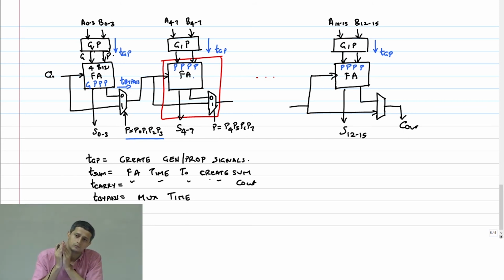Dependent on that, it means the arrival time of the output also will not count, like the input is changing, but the output is not changing for that particular case. Correct. So the arrival time of output, we don't include that case. Correct. Because it's a max kind of thing, right? So therefore, the worst case guy will determine it.